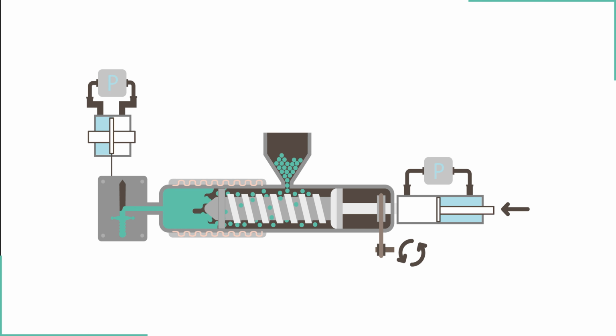During injection, the pressure acts across the mold surface onto the mold parting line. This force is opposed by the clamping force, which needs to be high enough to prevent mold breathing and flash formation. Potential mold breathing can be detected with fluctuations in the clamping pressure. Woojin does not need any additional sensors or special hardware to detect these fluctuations.